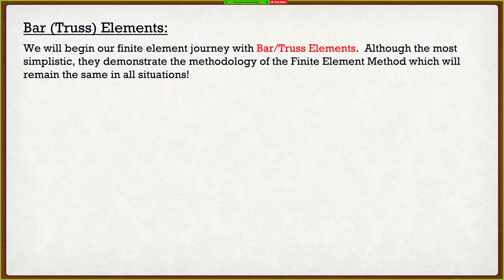So the first thing that we're going to do to show you guys this finite element method, this lecture in general, is just more of a nice introduction to the finite element method. Next lecture is where we start talking about the actual beefy stuff. This lecture, we're going to discuss bar and truss elements. So before we begin our actual finite element journey, we're going to begin with bar and truss elements because they are the most simplistic. Again, these elements just deform laterally. That's it. There's going to be no shear. There's going to be no moment, nothing like that. It's as simple as, can it expand or is it going to contract?